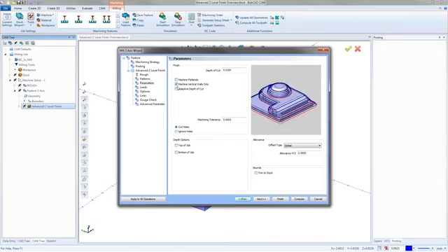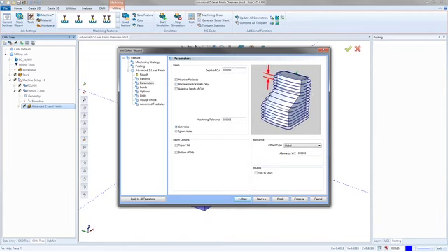Machine vertical walls only cuts the vertical walls. If there's any sort of taper or curve to the wall, this toolpath is going to ignore it now. And then we have the adaptive depth of cut. So if this is our normal depth of cut, the areas where we're going to get a bad finish is where the toolpath kind of flattens out, where it's not as vertical. This is the Z-level toolpaths, any of them, the Z-level rough, the Z-level finish, and then the advanced Z-level finish. They're very good at one thing, and it's cutting walls.